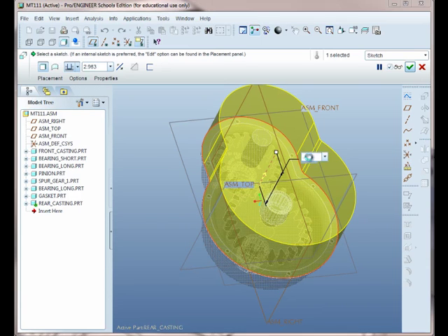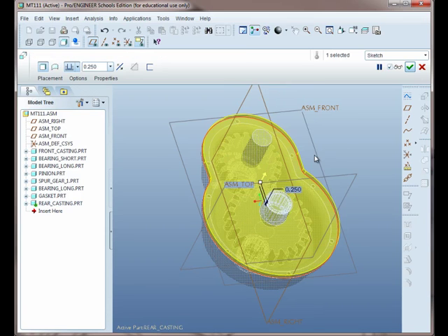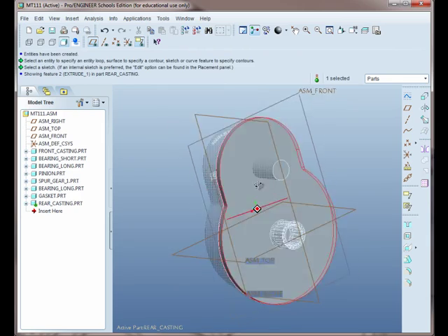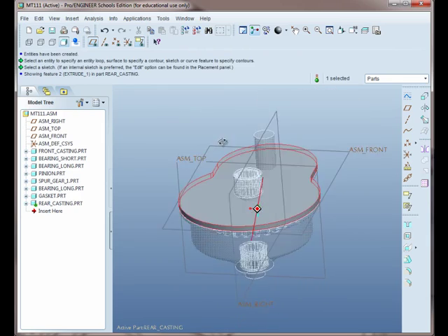And here we go ahead and we extrude this, and we can just double click on this number here and type in 0.25, hit enter a second time, and now we have the base flange created.